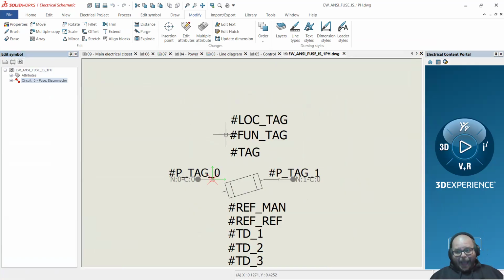The problem with that is that now this is going to look for normally open circuits. What if I bring in a Cooper Bussmann fuse holder and they actually used the fuse disconnector circuit? I don't know that. So it's better to leave the symbol and then match the manufacturer parts.